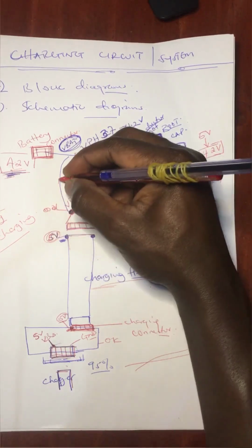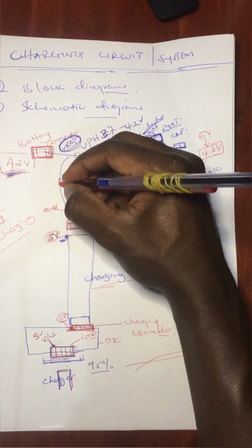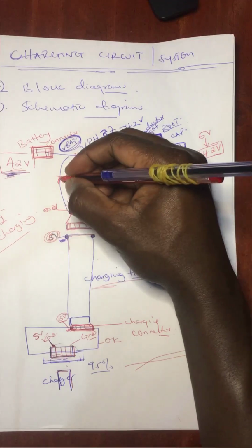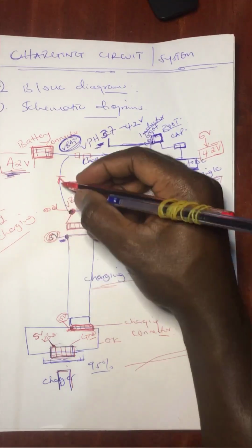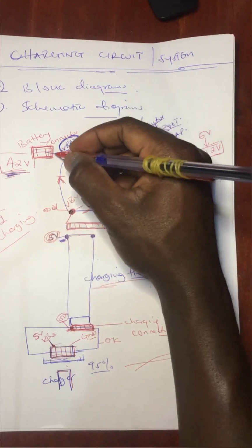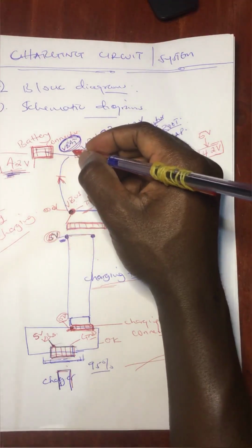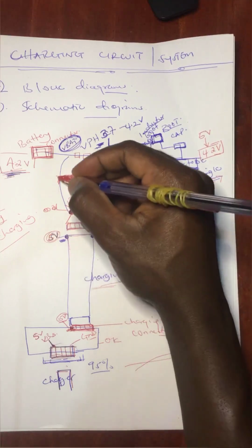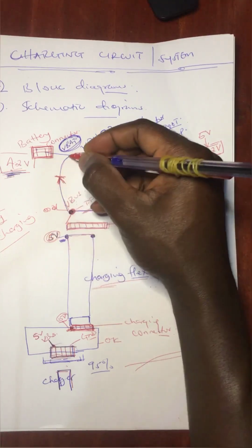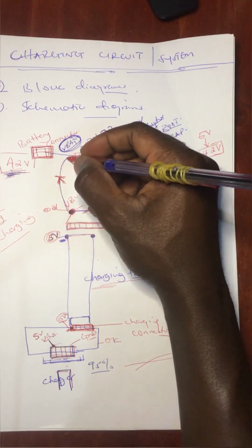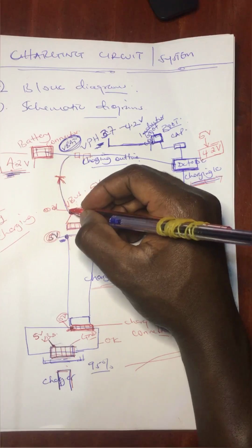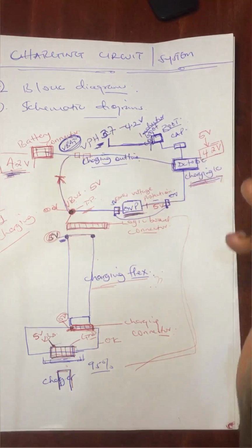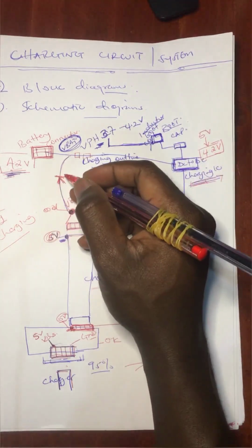Okay, now to solve this, there is a small component that you can put in between here, a diode, and I will show you that in the subsequent video, to make sure you don't have this voltage coming back to the VBus. So you put a diode that is going to stop the voltage from rebouncing back to the VBus, and you do that, your phone is going to charge perfectly and will not be on self-charging.